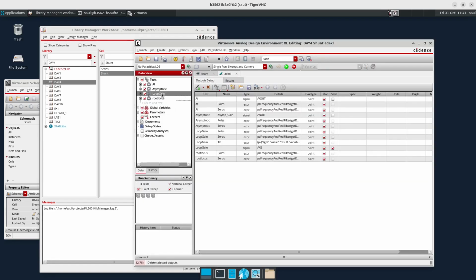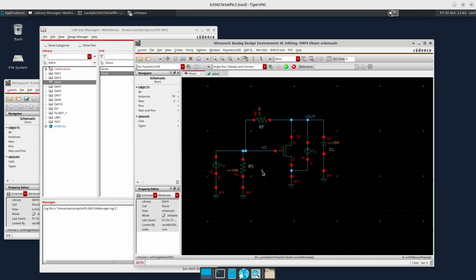And for the loop gain, I will be setting this one to 0, IS to 0. I will enable the test current. I will put 1 for this one, and then I will be running the AC simulation and finding the gate voltage. No, the source is grounded.